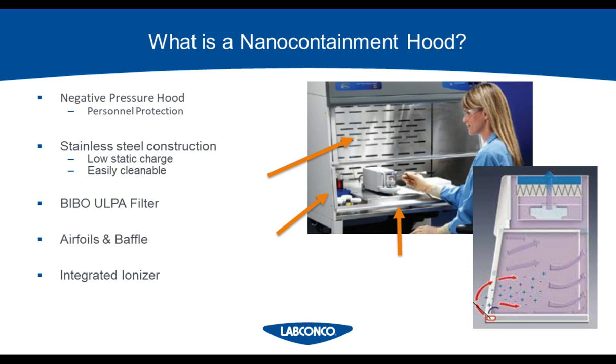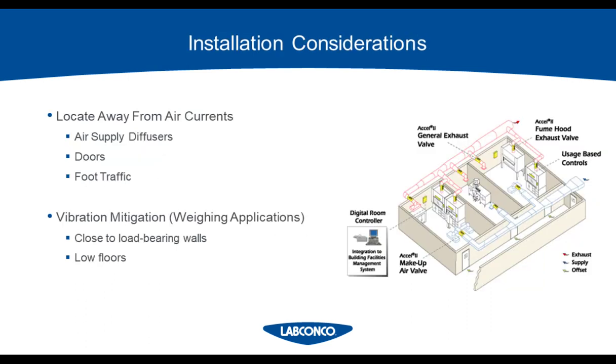One other thing that can be nice for nano containment to help with static is to integrate an ionizer. So if you can purchase a device that has an integrated ionizer, you can reduce the static and the strange behaviors that some nanomaterials exhibit. Sometimes they act like gases due to static, and with an ionizer, you can at least help reduce some of that static nature and help the hood contain at a higher level.